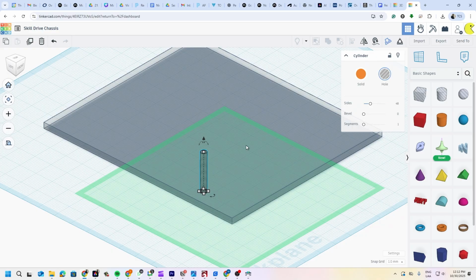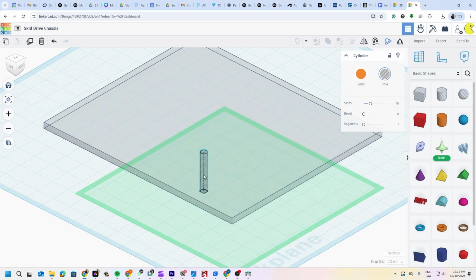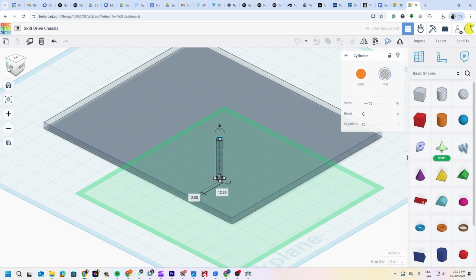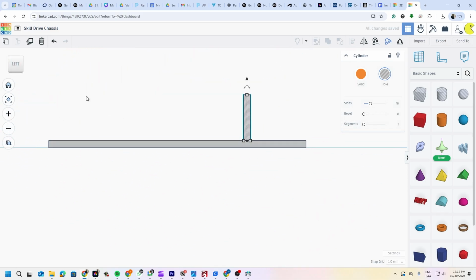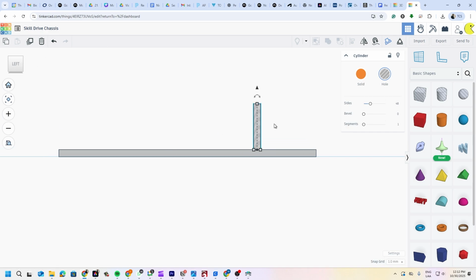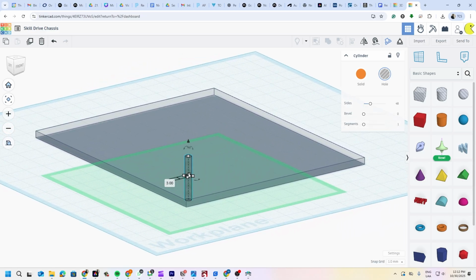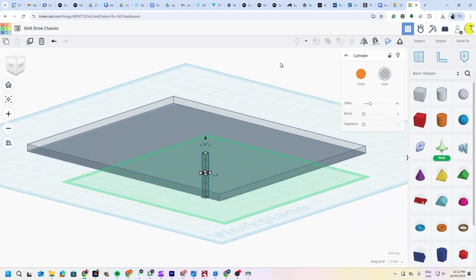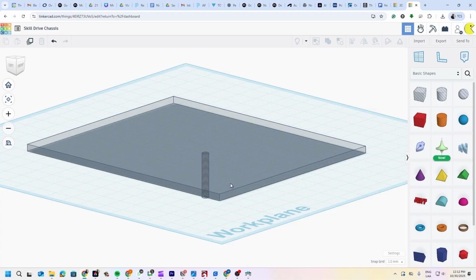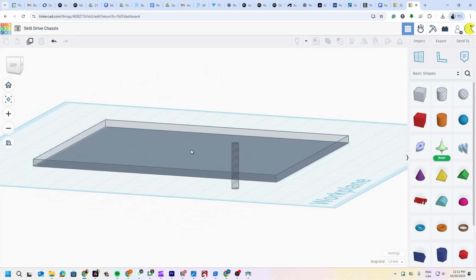because that's what's going to make us very efficient. First of all, I'm going to click on the left view. I should see it completely flat. This is important. You have to see it completely flat. And I'm going to move this cylinder inside the other object. So now the object is inside. And how do you subtract this object from this object?